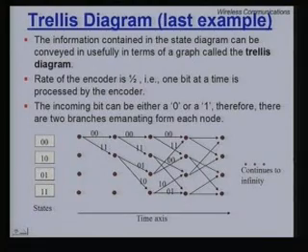A different bit stream will let me choose upper, upper, lower, upper, and so on. So, there is a unique correspondence between an input bit stream and a path in the trellis, which means, if you want to look ahead, we will see the decoding process is nothing but identifying the most likely path in the trellis. So, it is a search of the paths.